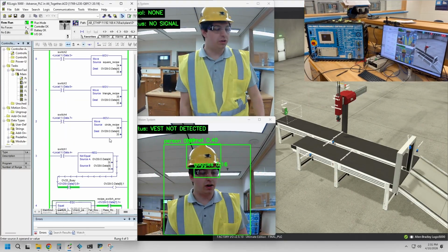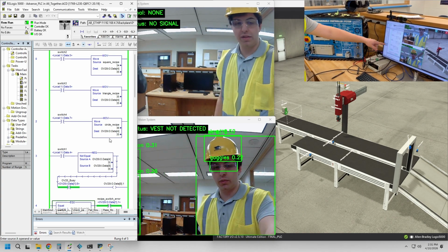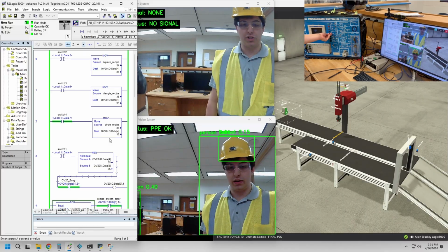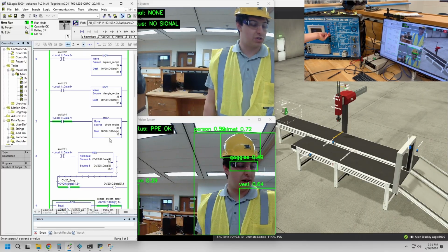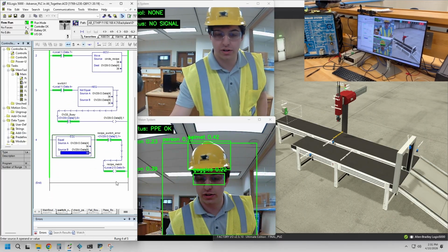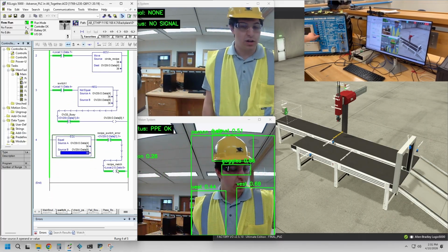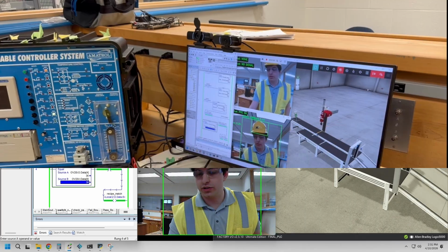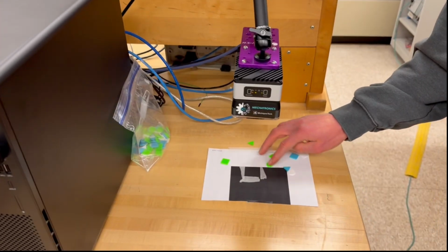For switching a part, which one we want to work with, I will want it circle. So we'll do switch 4, which activates the circle recipe, and switch 1, which locks it in for what the camera is going towards, and now recipe match. So I will undo those. So now we're searching for circles. So then if we put a good circle